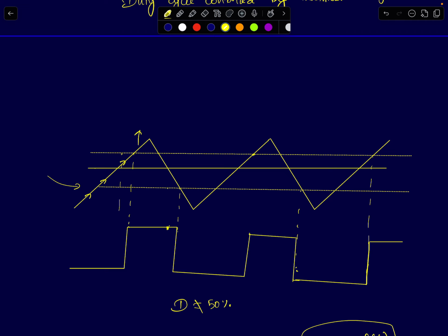Okay, remember it's a periodic signal, which means it's repeating, and this is your entire time period. Let's assume this is minus V peak and this will be plus V peak. The point where it starts from the negative peak voltage and reaches the positive peak voltage, the time it takes. Previously it was 1/2 cycle, now it's greater than that because it's increasing slower in 1/2 cycle. So it's going to take more than T/2 seconds, which means the waveform is not purely symmetric. It doesn't exhibit odd symmetry.